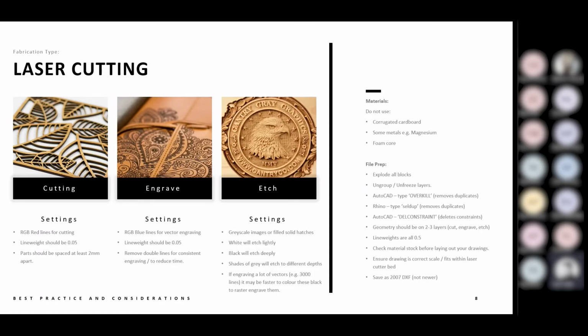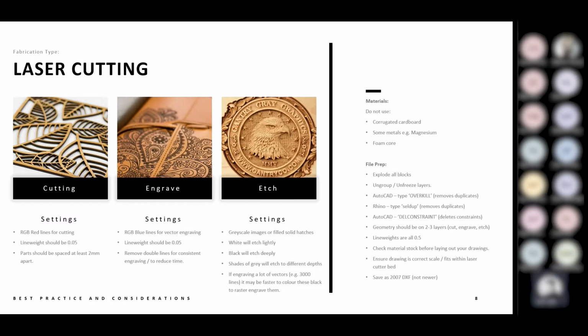Ungroup and unfreeze any layers because they won't be read by the laser cutter. If you're using AutoCAD, you can type in the command overkill, and this will remove duplicate lines. Or you can do the same thing in Rhino by typing in SelDup or select duplicates.